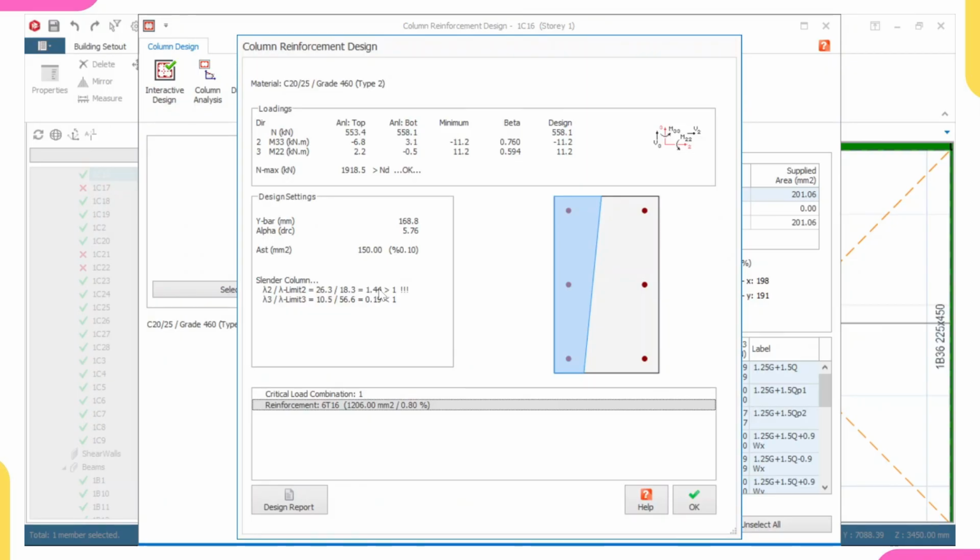So slenderness is just a ratio of square. It means that your building should be more of a square for that column not to fail in slenderness. And also remember, let me explain something. Column fails in two methods. We have two types of column: a short column and a long column. A short column fails by crushing, that's squashing. It's just like as if you crush something or squash something, while a long column fails by buckling. And it is from that buckling, that long column, that we get the slenderness ratio.